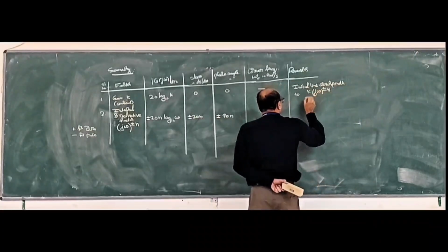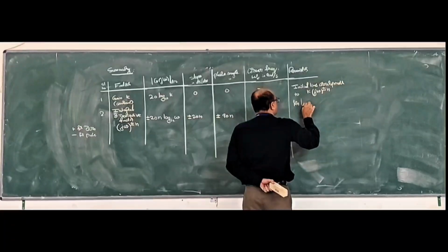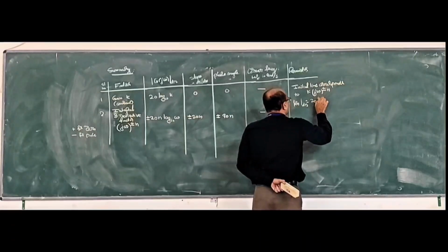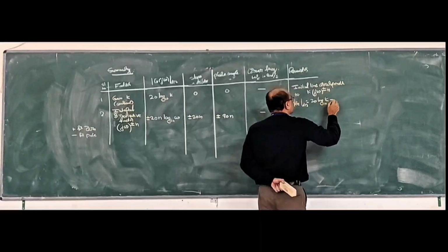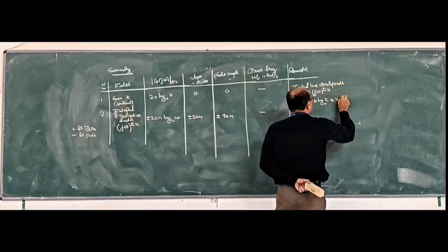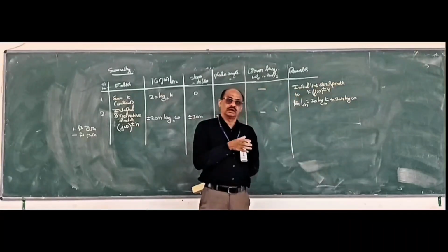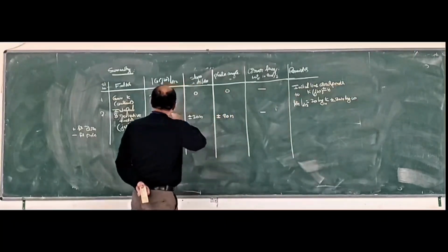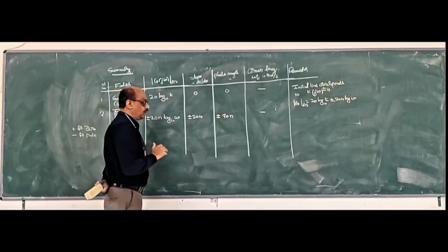Now, using that, what is the gain? Gain in dB for this is 20 log K plus or minus 20 n log omega, which is the gain of the initial line. The initial line you must take combining these together.